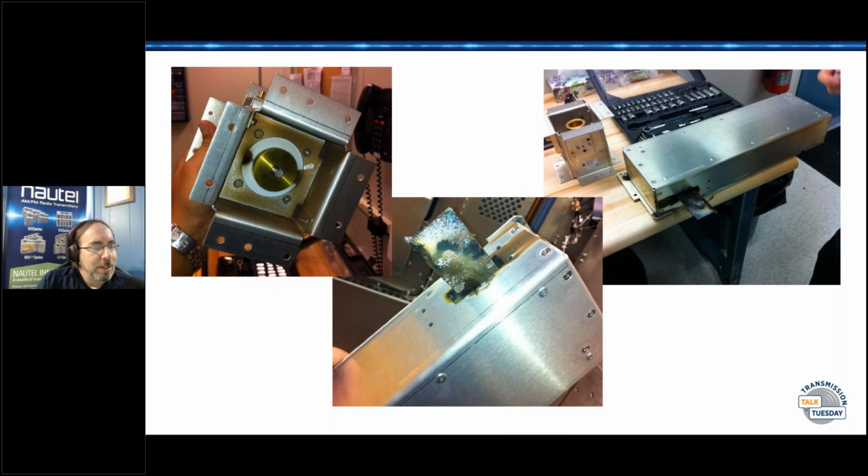Hey, Jeff, can you hear me well? Hey, very well. Good. Yeah, so this was a brand new transmitter. It had been on the air for about 3 months, and it seems like the little joint, the 90-degree between the output of the combiner to the output of the transmitter, shook itself loose. And eventually it started arcing and melted the transmitter from the inside.